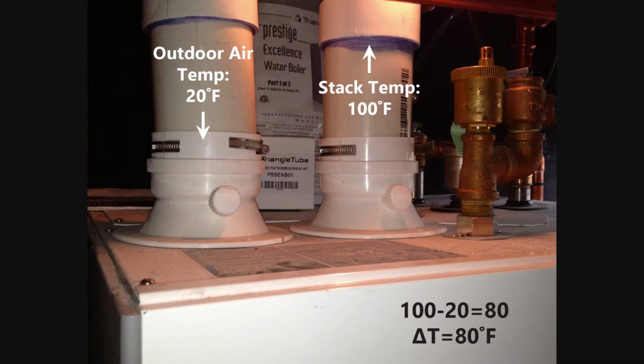In the winter, even much colder outdoor air temperatures. So the actual delta T can be quite different. Here we have 100 degrees in the stack, minus the outdoor air temperature of 20 degrees Fahrenheit, gives us a delta T of 80 degrees Fahrenheit. That's a big difference in measuring the delta T and has an effect on our true combustion efficiency calculations.